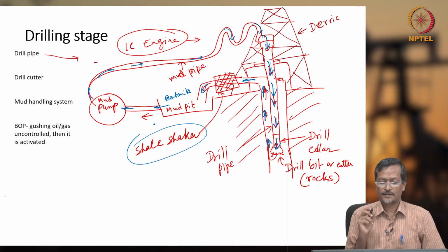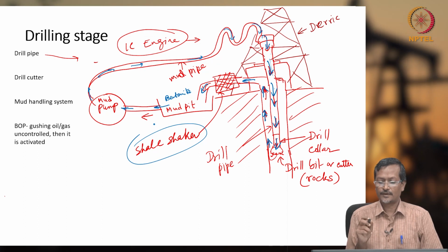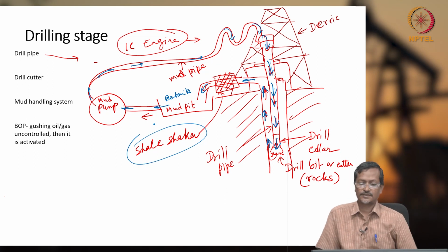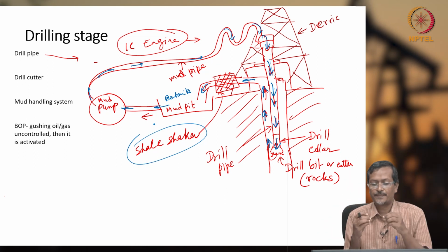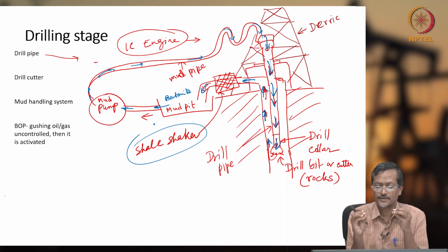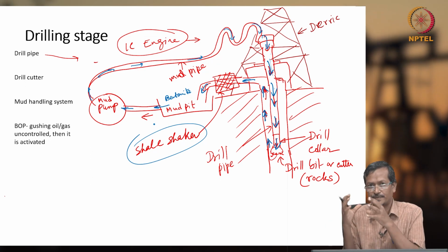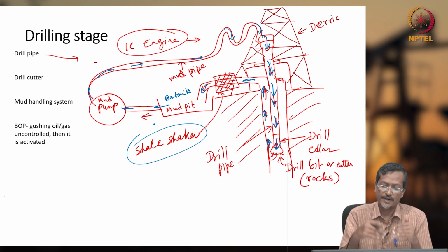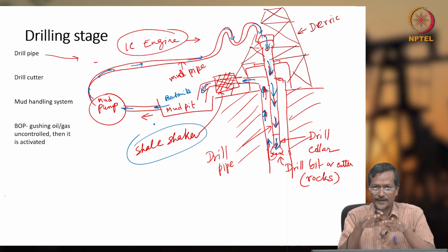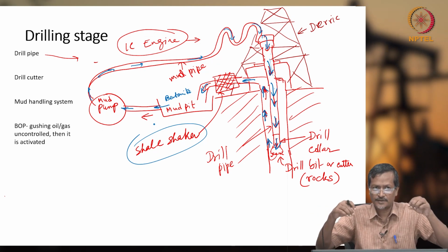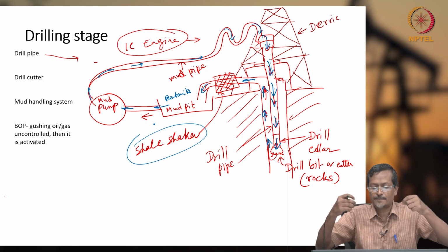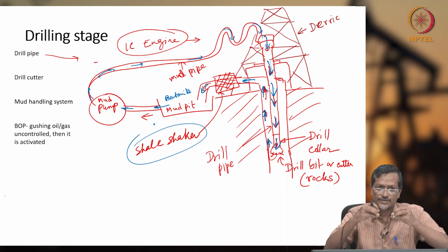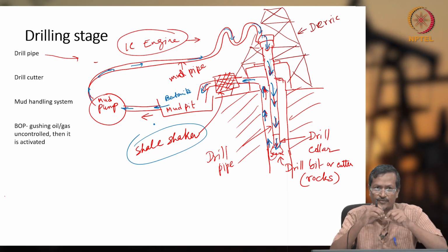Okay. But before that, sometimes there will be a centrifuge, because of centrifugal action you separate smaller rock particles from the mud. So once you separate the bigger particles and the smaller particles, you store that same fluid in the mud pit. The mud pit stores it for a certain time, so that any further smaller particles will settle down there. From the mud pit you again mix in certain desired chemicals if required.